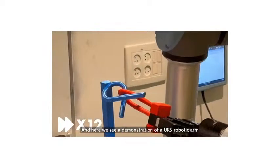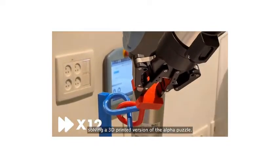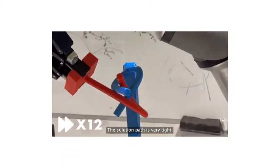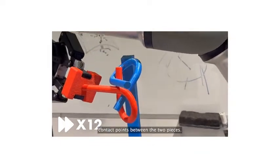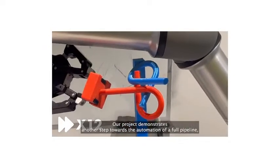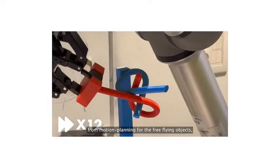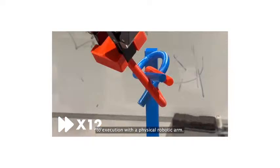And here we see a demonstration of a UR5 robotic arm solving a 3D printed version of the alpha puzzle. The solution path is very tight, as our motion planning algorithm intentionally maintains contact points between the two pieces. Our project demonstrates another step towards the automation of a full pipeline from motion planning for the free-flying objects to execution with a physical robotic arm.